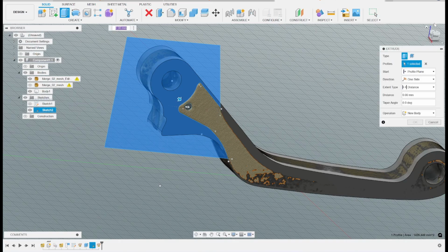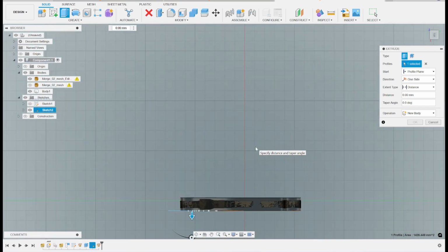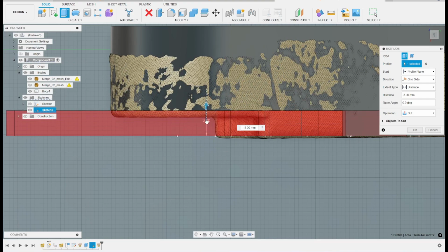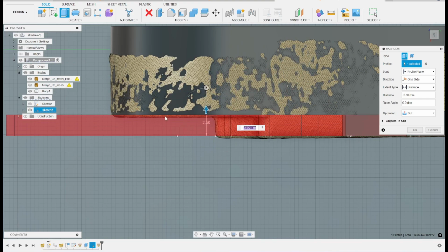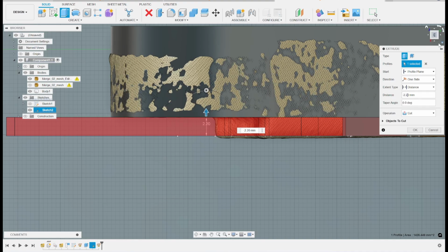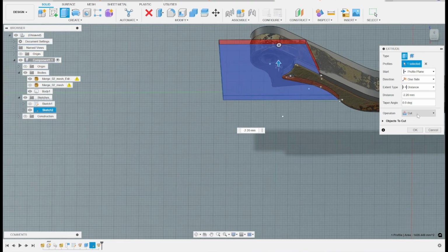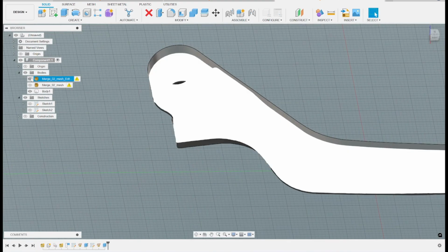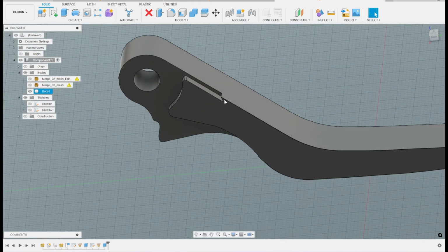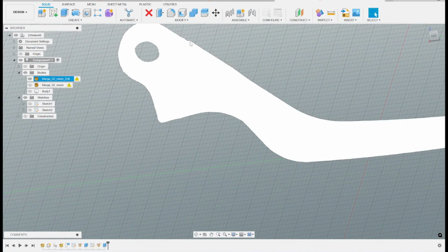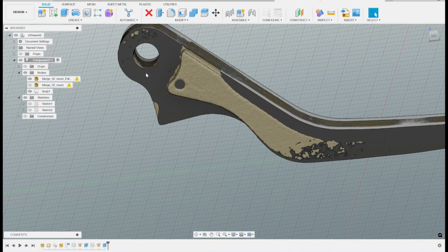We'll extrude this. The new sketch we just did. We want to extrude it up to this body. Right there looks fine. We're doing a cut for this. So that cuts it in. This portion here ideally should follow that, but just for this example, we'll just leave it like this.